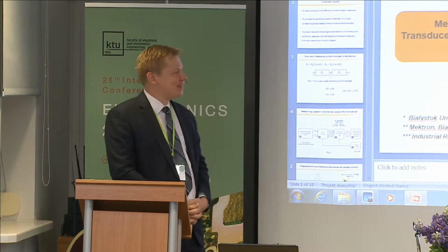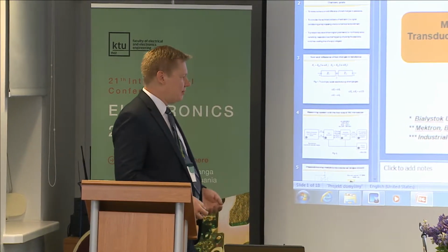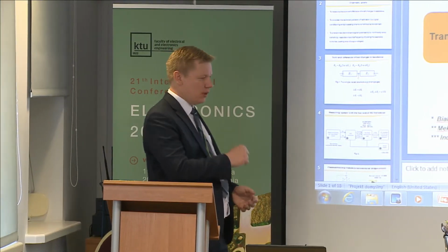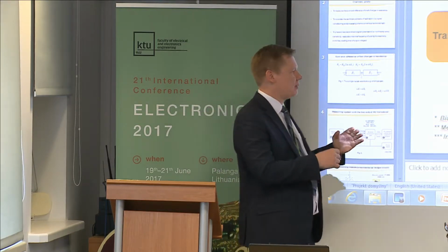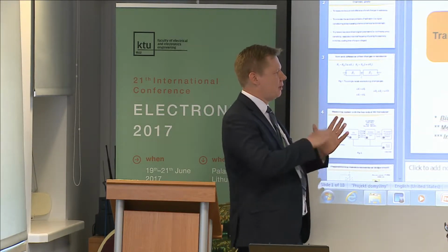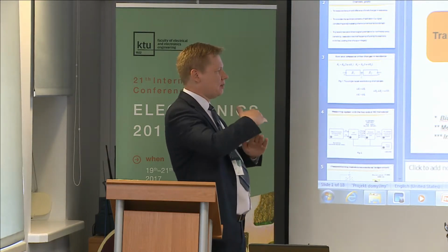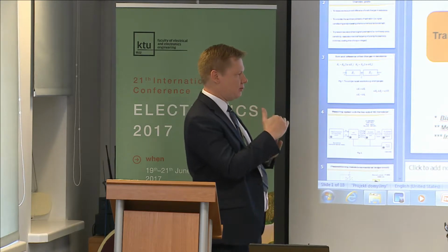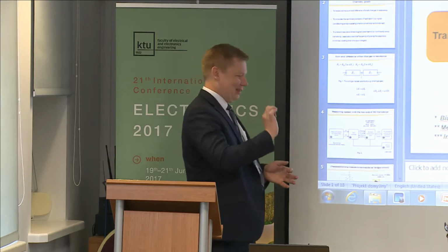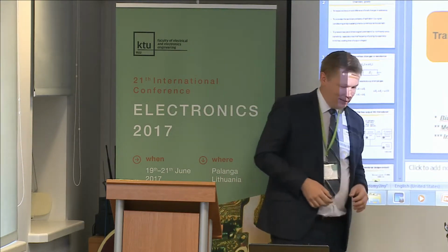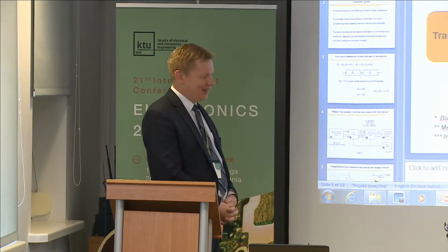And do you think you can cope with this nonlinearity with this device? Yes, probably. Usually, in classic metrology, we have Wheatstone bridge and quarter bridge, for example, half bridge, and sometimes we can compensate nonlinearity of sensor with nonlinearity of circuit, and this final line is more linear.